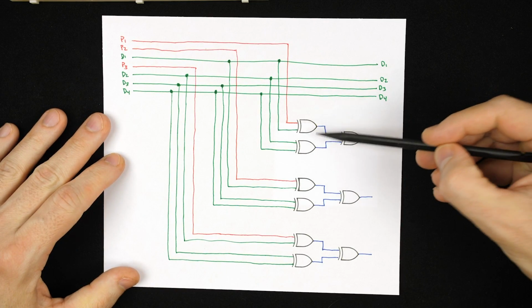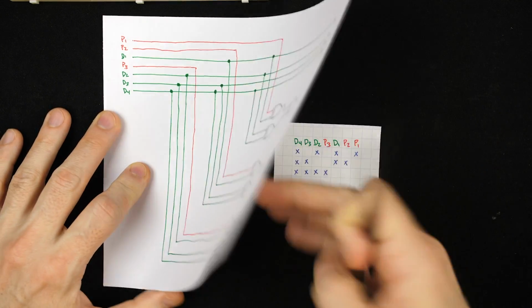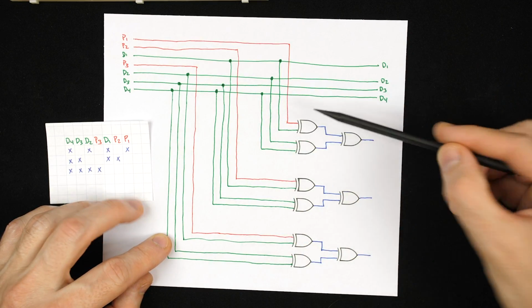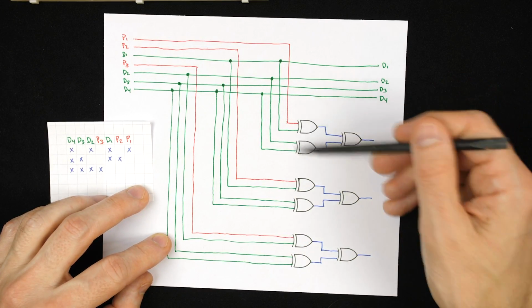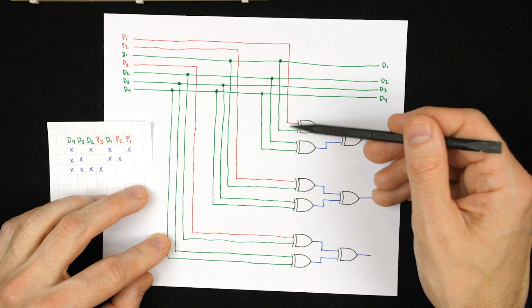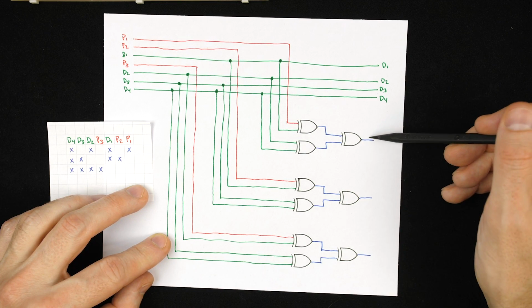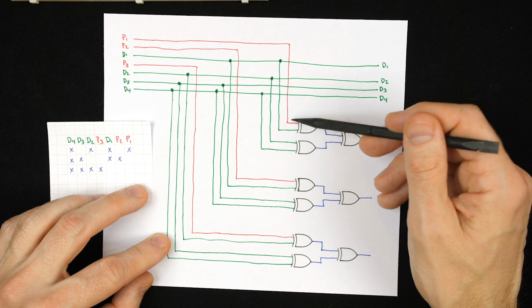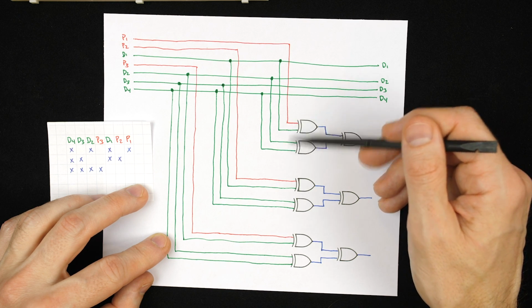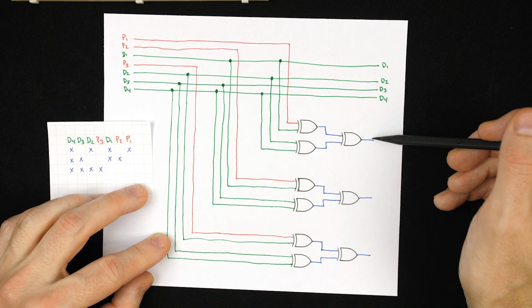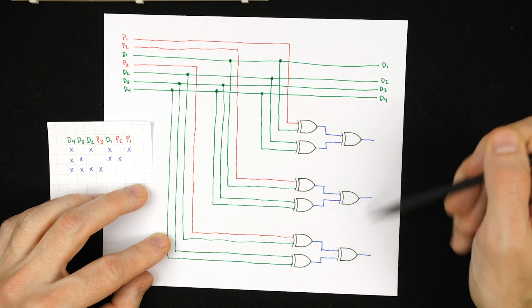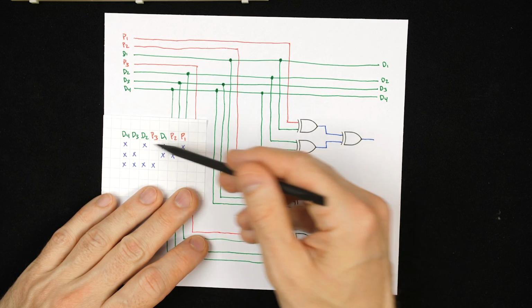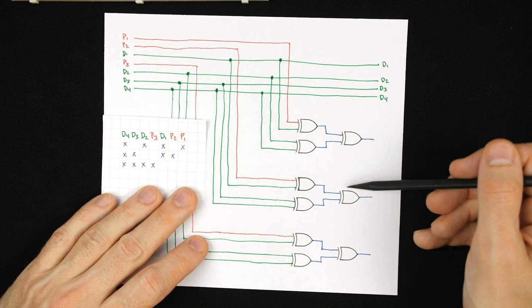So what we'll do is we'll have 3 sets of them to compute the 3 different parity bits. This first set here is for parity bit 1, and it's going to have 4 inputs here. Basically what this is going to do is XOR them all together. So if there's an even number of 1 bits coming in here on the left, then the output will be a 0. But if for some reason there's an odd number of 1s coming in here, so basically either 1 of these or 3 of these are 1s, well then the output here is going to be a 1. And so a 1 on any of these indicates that that parity bit was wrong, or there's some kind of problem that involves that group. And so we just do that for the 3 different groups.